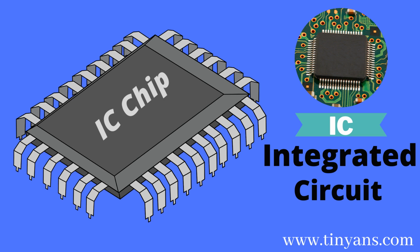Multiplexer and demultiplexer. Multiplexers, mux, and demultiplexers, demux, are common examples of combinational logic circuits. Multiplexers select one of several input lines and route it to an output, while demultiplexers distribute a single input to one of several output lines based on control signals. Decoder and encoder. Decoders are used to select one of several output lines based on a binary input code, while encoders convert an input into a binary code.